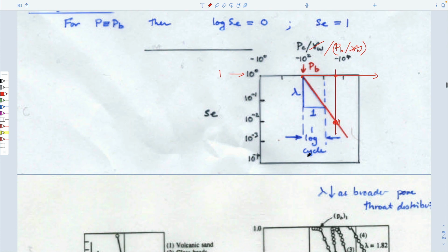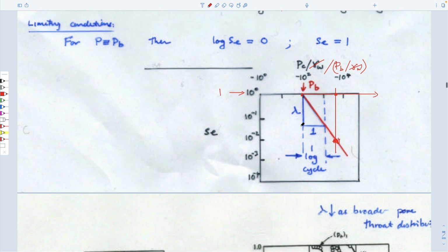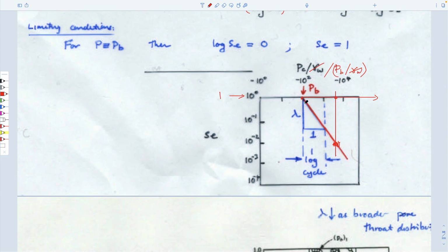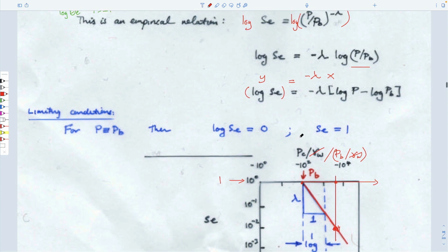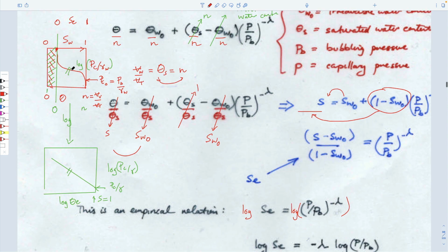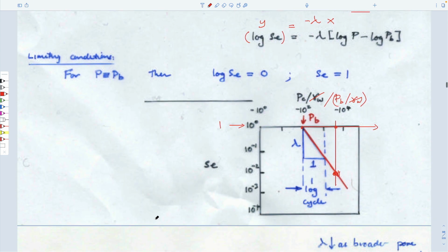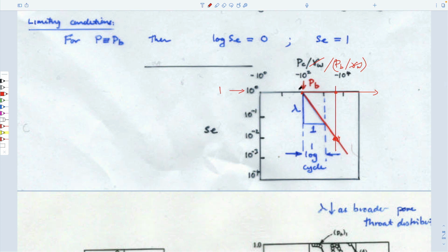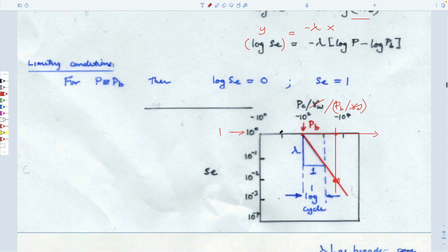And that's useful to us because it's a convenient way to represent the relationships. It's not a random curve, which we don't really understand very well, but a straight line. And so it's quite easy to look at the features of that straight line. And I suppose there are two ordinates we'd be interested in. One would be the location at which a bubble of air first goes into the system. And the second is the gradient of this line as we go up and down here.